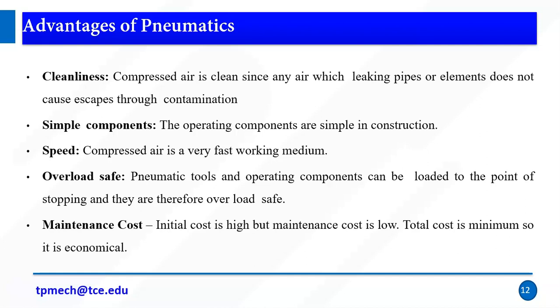Simple components: the operating components are simple in construction compared to hydraulics. Speed: compressed air is a very fast working medium. Overload safety: one of the main advantages in pneumatic fluid power is overload safety. If you use electrical or electronic sources and an overload happens, the entire components will be damaged. But with pneumatics or hydraulics, it won't damage the components. It will stop the process. So pneumatic tools and operating components can be loaded to the point of stopping, and they are therefore overload safe.